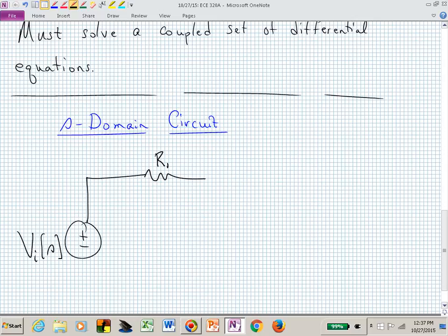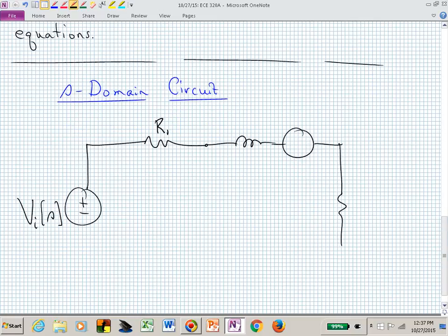We had a resistor, that was R1. Then we had an inductor. We had another resistor, R sub 2. But now that inductor, we're going to give it an impedance in the frequency domain. It's now S times L. And we have another source appearing, which has a value for a source as the inductor value L times I sub L of 0 minus. We have our capacitor that was in the center branch. It now has an impedance of 1 over SC,